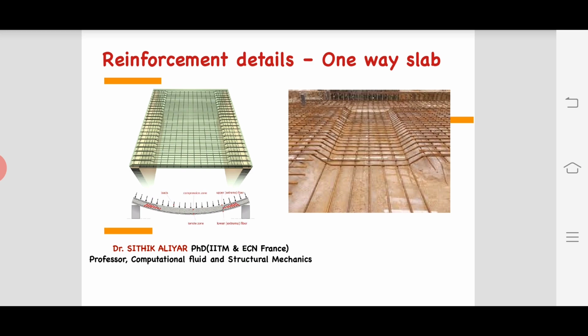So if somebody asks you what slab design means, you are going to tell the width and depth. The depth is fixed for most of the cases. Width is based on what? Based on the building plan, right? So width is already known, you have to cover the total building. And depth is mostly 100, 150, that is standard. If you are going for the top floor, second floor, third floor, then there will be a big difference, we can go up to 175 to 200. So width and depth is constant.